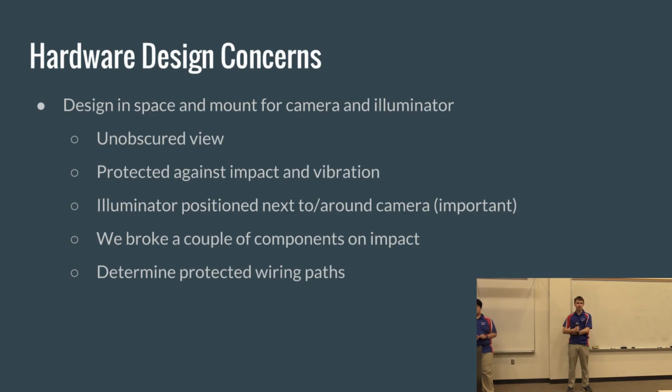So make sure your LEDs are in a secure place, or just strong enough to not get broken by strong hits. And then another important thing to consider that you usually won't notice until it's too late: your wiring. Especially for flywheels, the flywheel shooters would move up and down and aim, and that involves a lot of moving parts. And when you have a camera on there, that camera has to be plugged into your system. And if that wiring just kind of goes wherever it wants and isn't well placed, it's going to get cut when it rubs against other pieces.